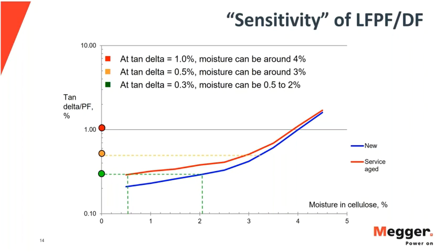So this presents a challenge since it's not a straightforward task to quantify the aging of a transformer. You can't go on years in service to quantify the aging of a transformer. It's simply not reliable because environmental and system variables, maintenance, and other factors all have a role in how the insulation is going to age.